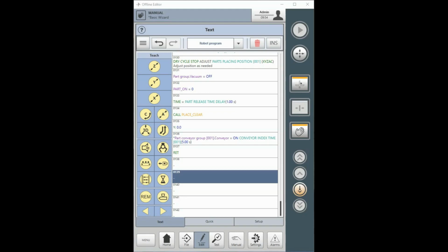Counters must contain a whole number in the range of minus 2,147,483,648 to positive 2,147,483,647. Common uses are: A, to count up or down, of course; B, as a memory bit to remember if something has happened or not. When using them for this purpose, we typically store either a 1 or a 0 in the counter; C, to perform math in our program.